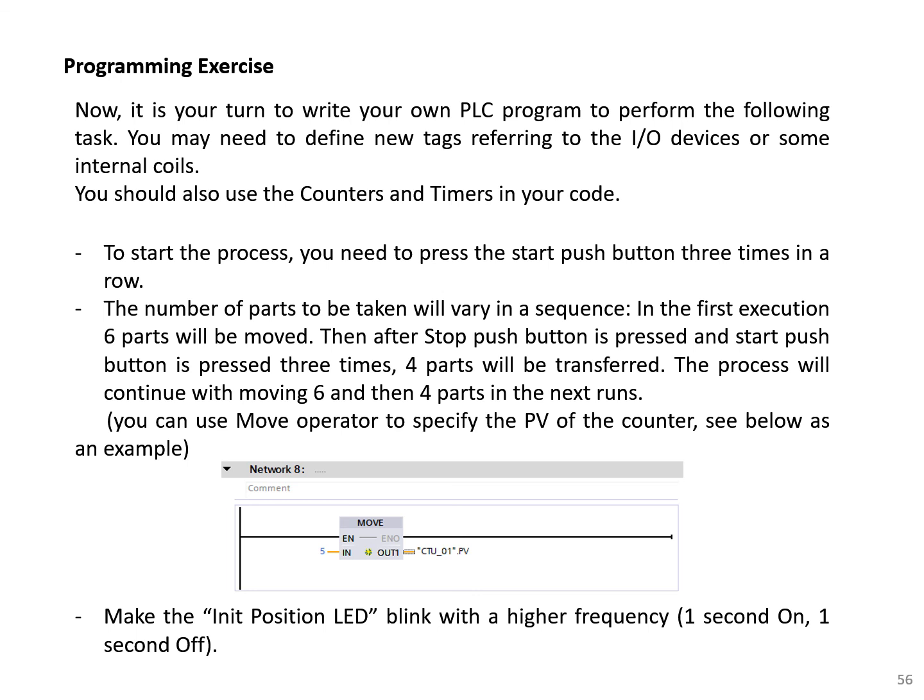You have a programming exercise. Now it's your turn to write your own PLC program to perform the following task. You may need to define new tags referring to the I/O devices or some internal coils. You should also use the counters and timers in your code. To start the process, you need to press the start push button 3 times in a row. So we need a counter here to count that 3 times of pressing push button.